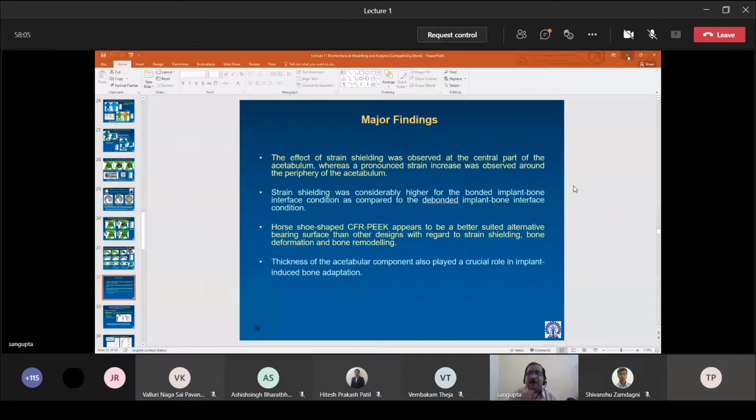How to rectify that? You generate a very thin outside layer, say 0.5 millimeter, maybe 0.8 millimeter, an outside segmented layer of cortical bone, and then you force it with a value. So now you get rid of this partial volume effect, so that you don't end up with anything beyond the boundaries of the CT scan.